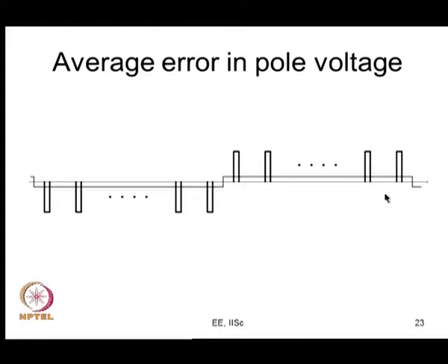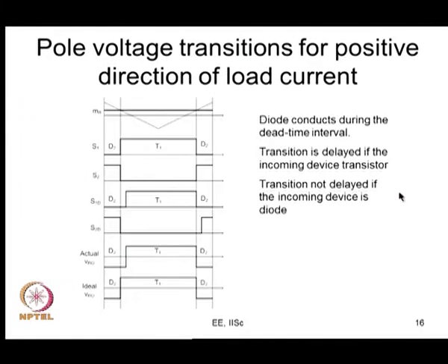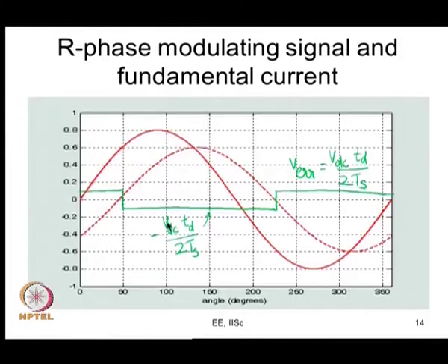This square wave gives a measure of how much damage is caused by dead time, or how much of the fundamental and low frequency components have been introduced on account of dead time at the inverter output. This was the reason I drew this before, when I did the sinusoidal current. All that I have said now was the basis by which I did this. So when I do this, what happens?